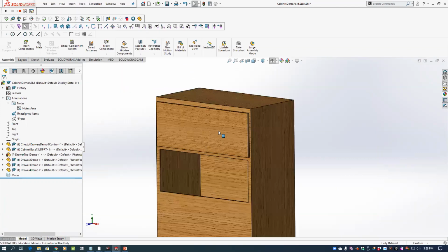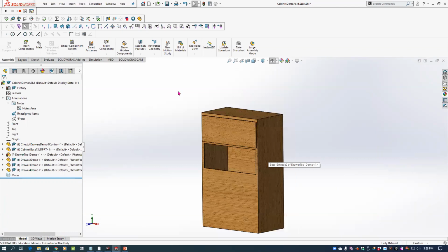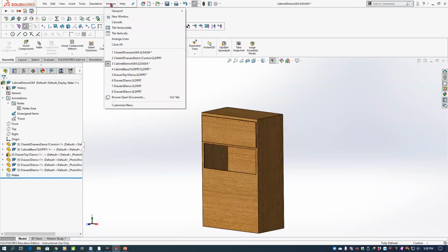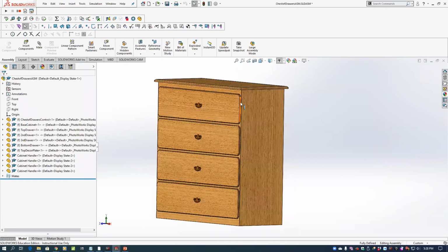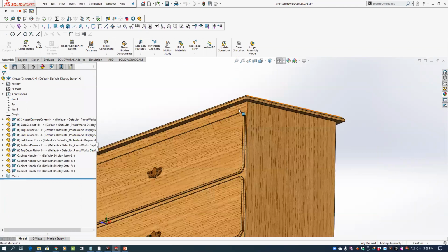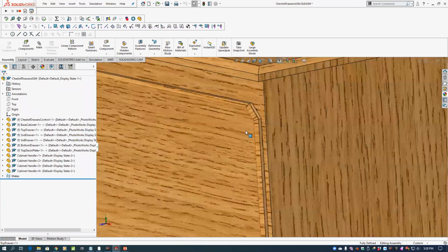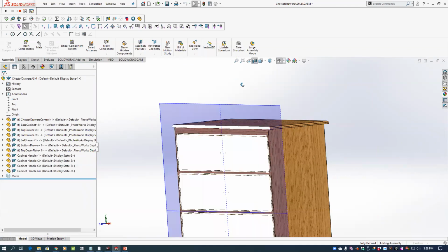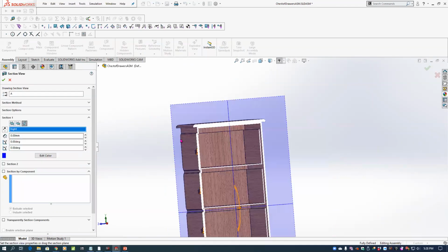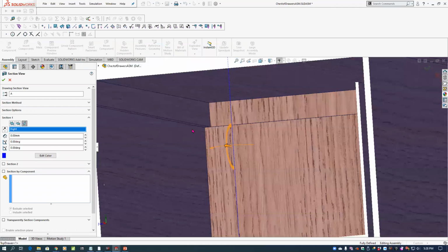And I can continue doing those kinds of procedures to build the whole cabinet, add the other features on there, like I did with mine, to add all of the other features, add a top panel, and add cuts on it to make it more realistic. And you can see that by doing it this way, I can maintain clearance in there.